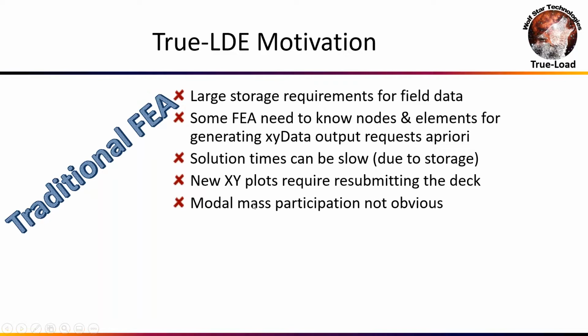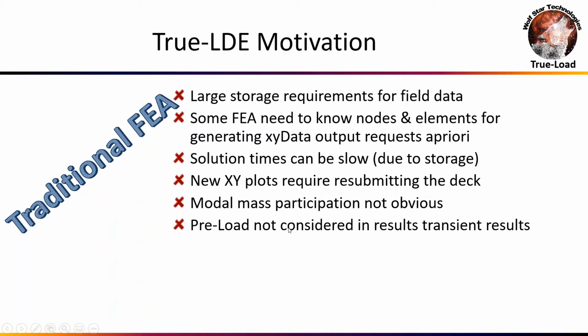And the modal mass participation is not always obvious when you do these solves, and the preload's not considered in your linear transient results. And I think most people don't realize that, but when you do a linear transient analysis, the residual effects from the preload are not superimposed on your results. It does affect the mode shapes, but it is not part of your stress and strain solution. And I think that's a huge surprise to most analysts.